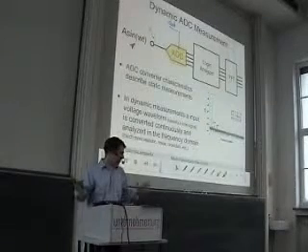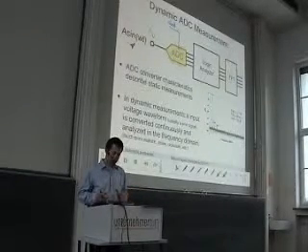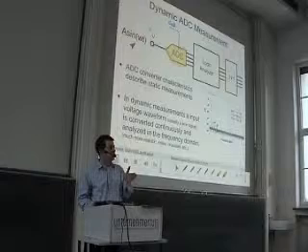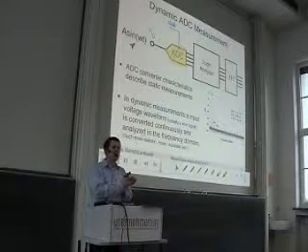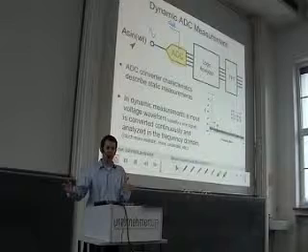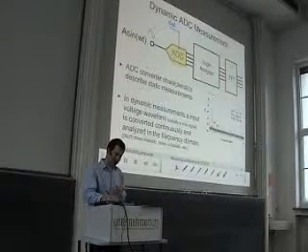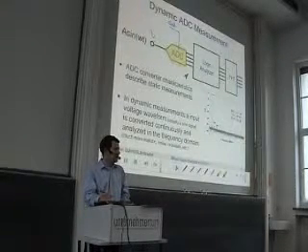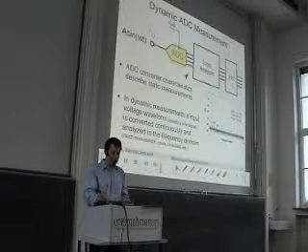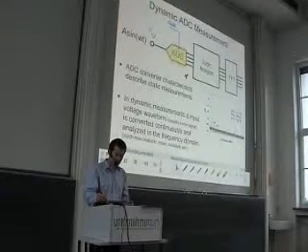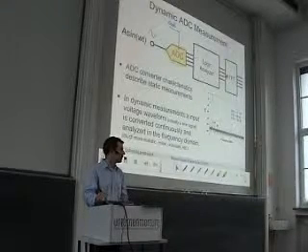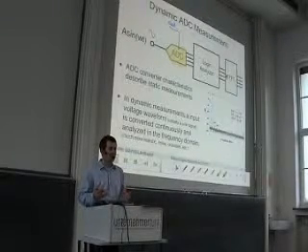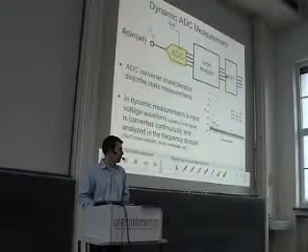And then we take, let's say, a data logger called a logic analyzer. This is a device that you have in your lab that you connect to the output of your ADC, and that records a long data stream of output values. So let's assume we have here a device that logs, for instance, 1 million values coming out of your ADC. And then you put these values into your MATLAB environment and do signal processing, which is usually an FFT. And then you get a spectrum of these results of the ADC.